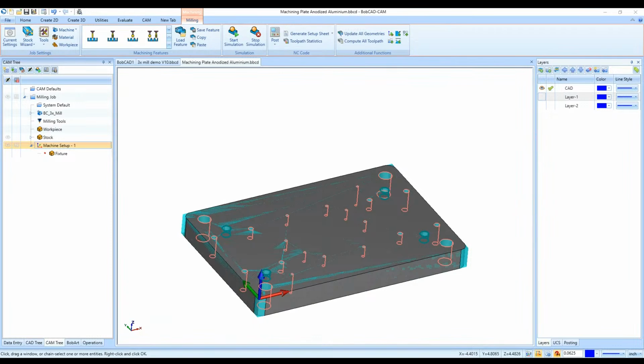Maybe I could add a tapping or a counterbore or a counterbore tapped hole in some of these hole sizes. I'll do a tapping for one of them here. These aren't really standard sizes for the diameters. I'll do the one that's at 630 here. So these 4 here, I'll do a tapping operation, for example. Do a tapped hole. And then I'll hit compute.